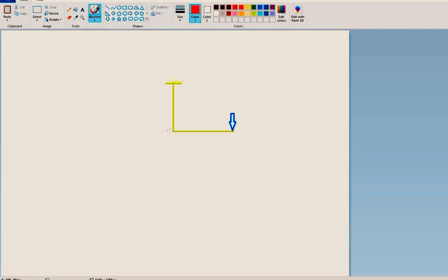Since there is no restraint here, this joint will move towards my left-hand side. So if we see like this, this is the fixed point. It will be fixed like this, and then it will move like this, and this is the right angle. This is the rigid connection, so here it will be like a rigid connection. It will be coming here, and then this will have the deflection like this. So if I see here, tension is on this side only.